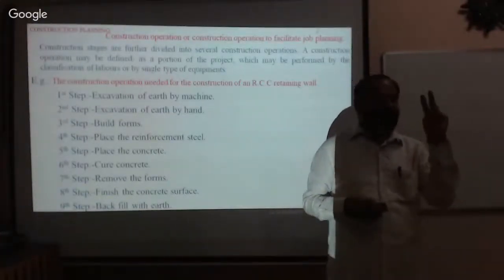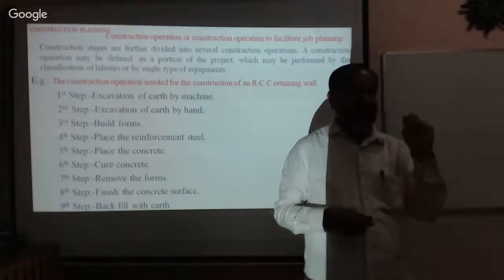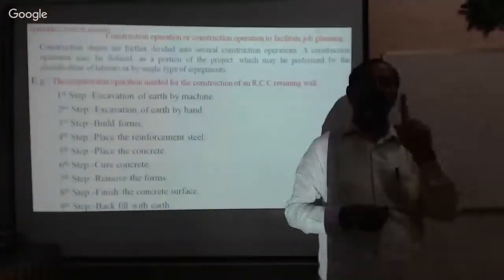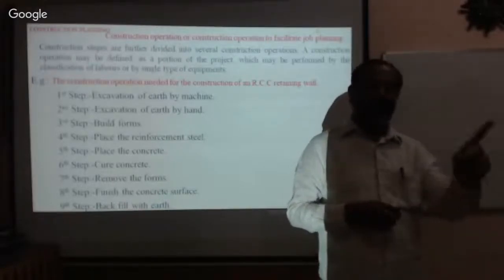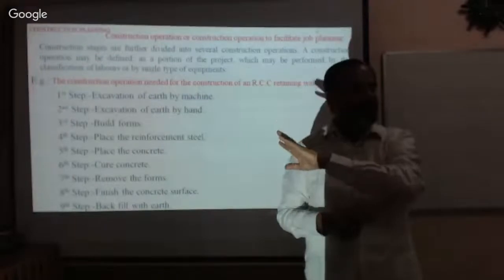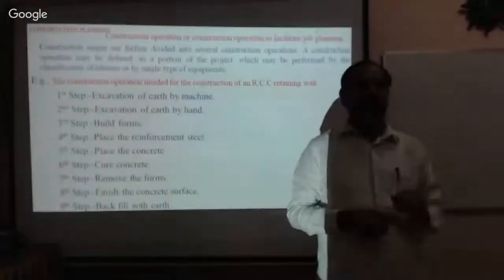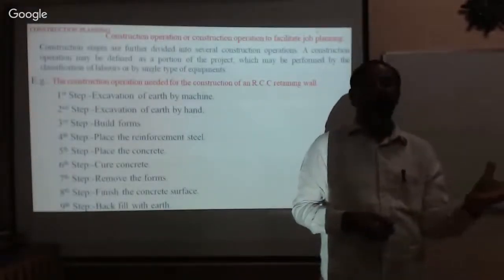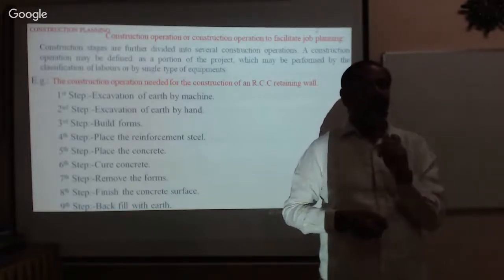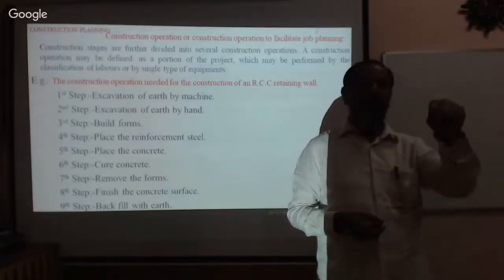Now first, what they did in the first stage: they went to the site and conducted the survey. That first job they have done. Then the contour map will be given to the architect to prepare the drawings. And another engineering team is investigating the soil exploration, that means where the foundation is to be.